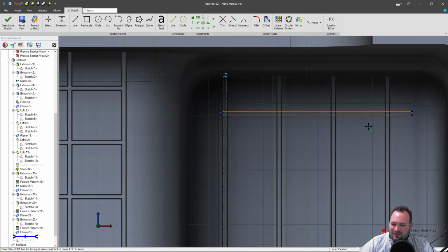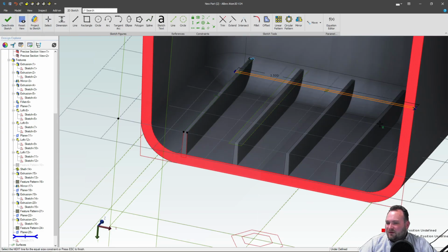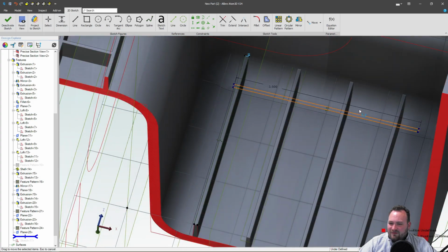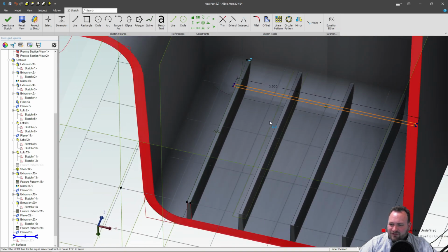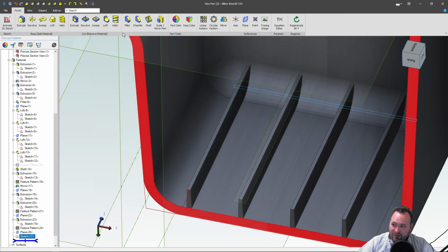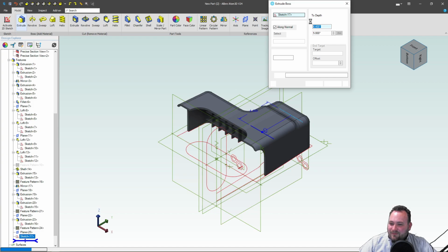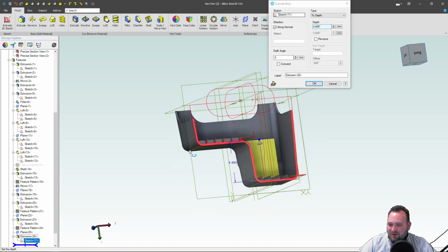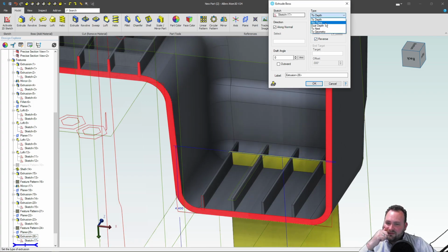And as you can tell, if I have a really fancy surface down here, I can come down and extrude to surface. We're going to call this defined enough. Again, you've already seen the consequences of not fully defining a sketch, so this is the same risk that I'm taking here in design intent. It's not best practice. It's just best practice for time, I guess. And now as I go to extrude that, look how much faster we are rebuilding. I'm going to do a reverse and then up to next.